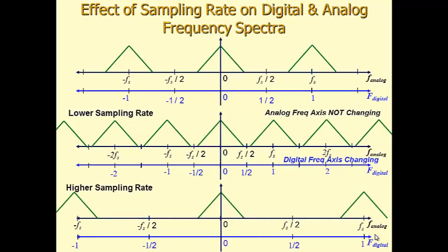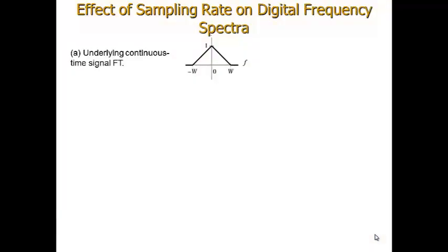So first thing I can do, as was done in the CD rate, is don't design with just a Nyquist rate sampling, but use a slightly higher sampling rate so I can put a gentler roll-off, low-pass filter in and still be okay. That's the least I should do. All right.